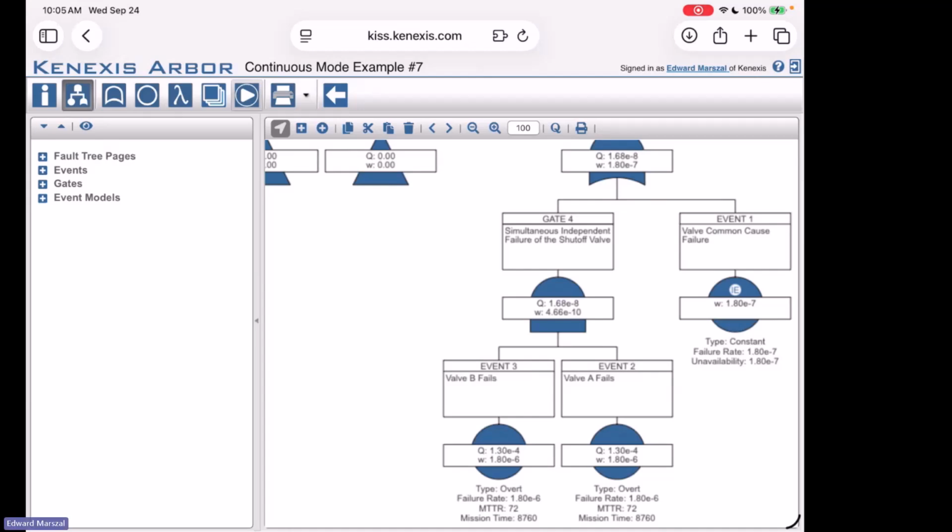Yeah, mathematically speaking, you will treat them the same way for DU failures. The only thing that gets a little bit interesting and confusing is diagnostics. Now, in my example, when the safety function fails, you're going to have a consequence within a couple hours. But let's say I'm challenging my safety function once every 6 months.